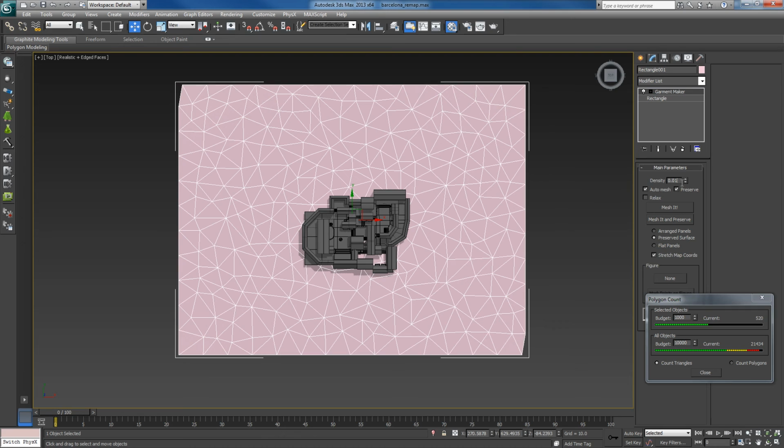So focusing on the density value here, we got to be very careful about this because small numbers are large. So if we think in terms that if we pump in a value of 1 into this box, we're going to double our resolution of our density. That's not the case. What's going to happen is it's a factor of like 100,000. All of a sudden you're going to go from something that's 520 to basically you got to turn the computer off because it's still calculating the topology. So small values to begin with.